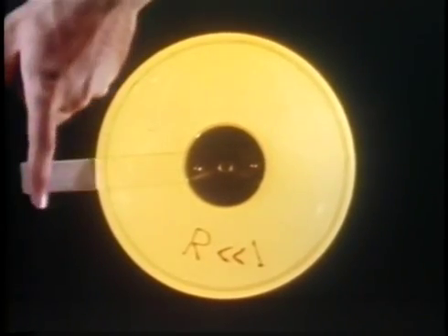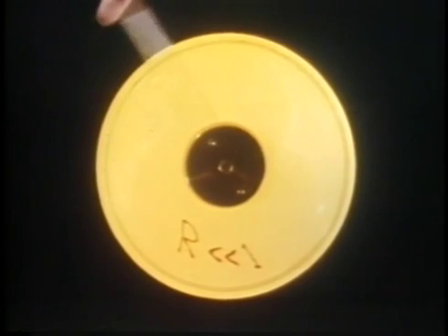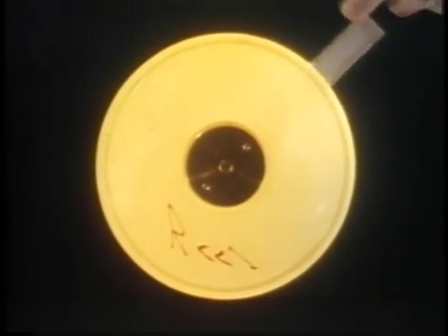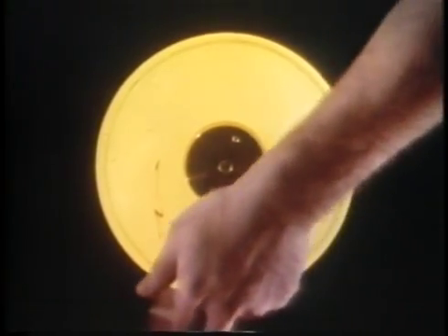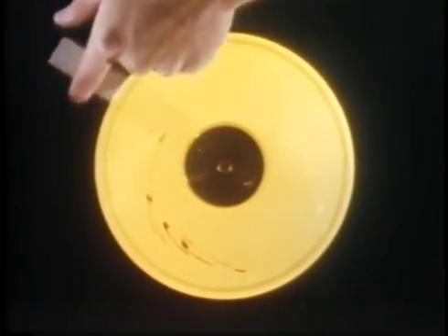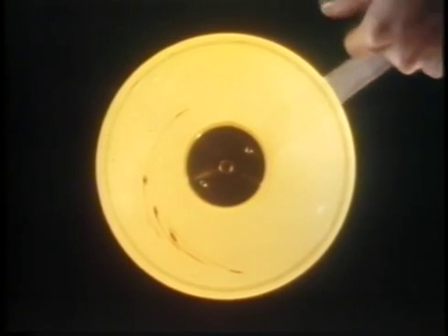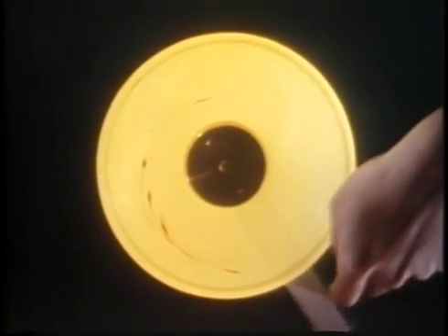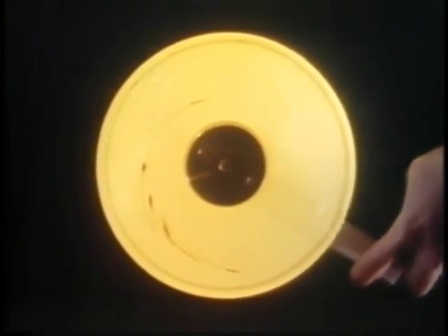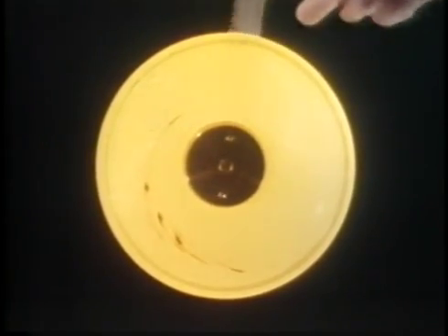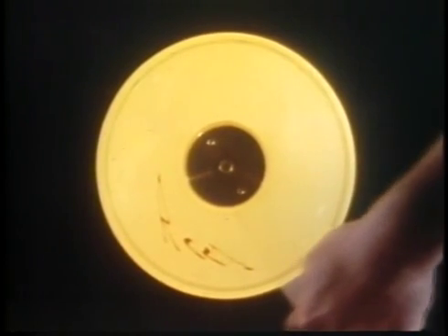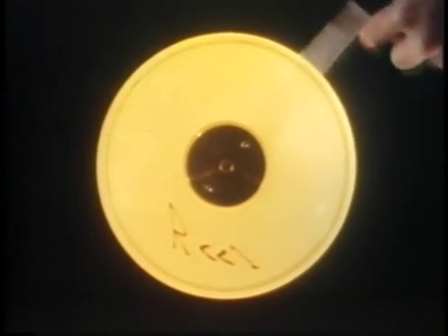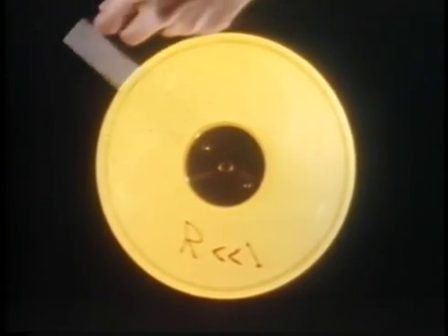During the forward motion, the boundary of the fluid follows a path determined at each instant by the motion of the wall. At these very low Reynolds numbers, particles within the fluid move when the boundary moves, and they stop when it stops. During the reversed motion, the boundary of the fluid retraces exactly the path it followed during its forward motion, and the particles return to their original position.